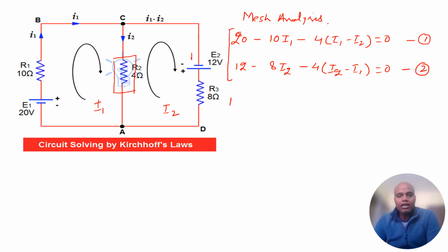Similarly, when I'm applying the KCL, let's understand that at node A, I'm taking this as my reference node. With respect to this A, I'm considering this node C as one of my nodes at a different potential. Forget about these branch currents, which are already denoted over here; we can formulate the KVL equations for those also, but it is not necessary. So for the KCL, let's take the node C at the voltage potential V. So V is the potential of the node C.